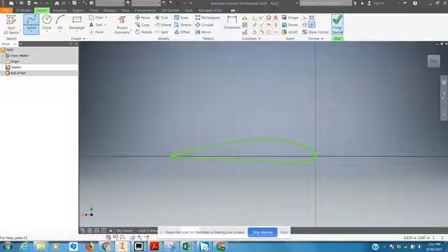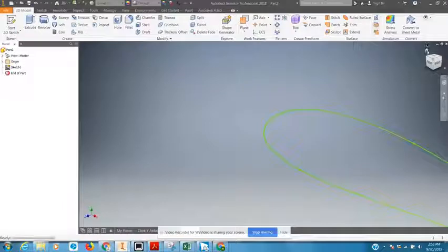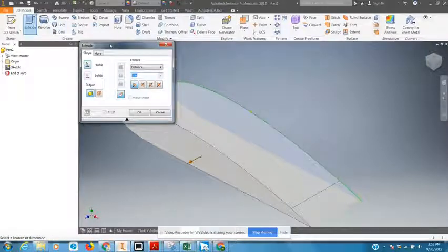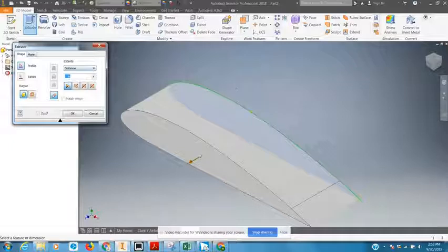And I'm going to finish sketch. And I'm going to select home, which puts us into that orientation. Then I'm going to extrude. Now that's always a good sign when you select extrude and it starts to extrude, because extrude will only work if you have a closed loop. And there's always a concern when you're selecting points around the loop that it may not be closed. But I see that it did close, so that's a good sign.